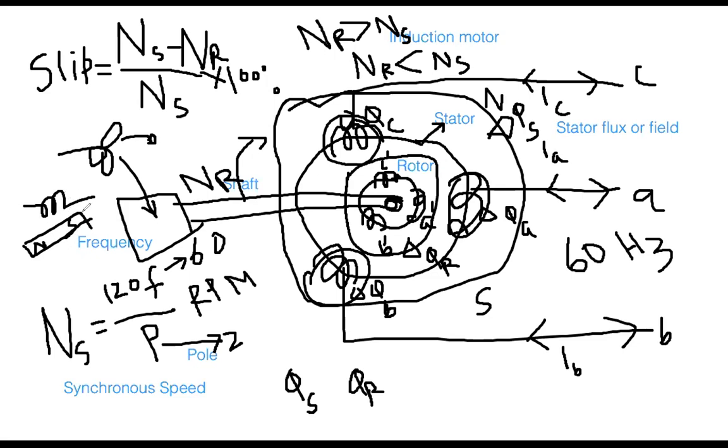Therefore, if you rotate both, then make some difference. Or you just keep one static, fully stopped. Either you fix the coil and move the magnet, or you keep the magnet fixed and move the coil. In both cases, the voltage will build up. So that's why, if you see the slip definition, this is my slip definition. If you make both equal, even though initially the motor started rotating, but with some arrangement you make both equal, what will be the consequence? Next time, there will not be any voltage on the coils because that is not meeting the requirement of voltage induced. There is no relative motion.